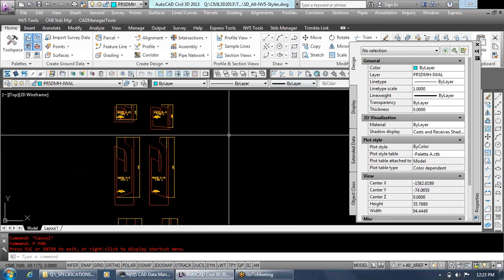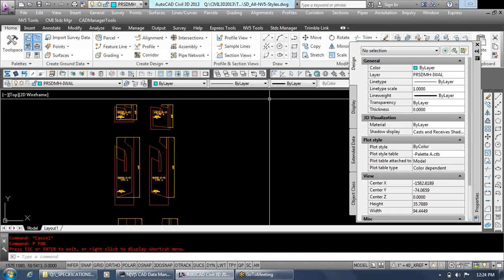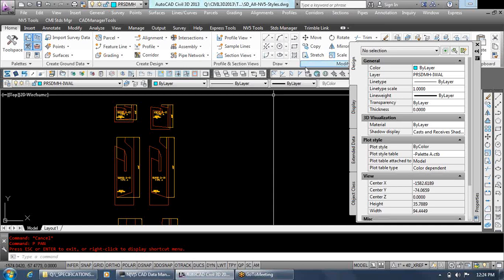So start thinking about how you want to name your Civil 3D objects, especially if we're developing a finished grade surface versus a datum surface or the rough grade surface, where a simple PO1 doesn't do enough for us. We need a PO1-FS or RG or some descriptor in our naming convention to really tell us what these surfaces, alignments, and pipe networks are. Next comment will be on pipe networks.